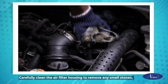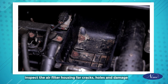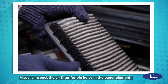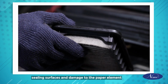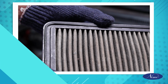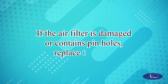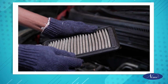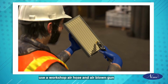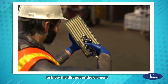Carefully clean the air filter housing to remove any small stones, bugs, and debris. Inspect the air filter housing for cracks, holes, and damage. Visually inspect the air filter for pinholes in the paper element, sealing surfaces, and damage to the paper element. If the air filter is damaged or contains pinholes, replace the filter. If there is a small amount of dirt in the air filter, use a workshop air hose and air blow gun with a maximum of 30 psi pressure to blow the dirt out of the element.